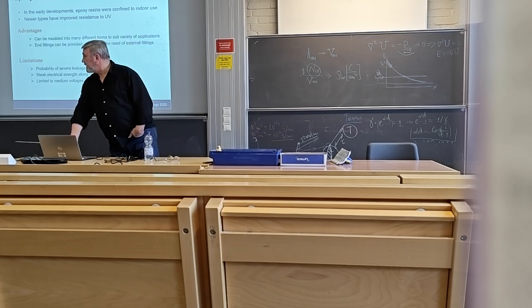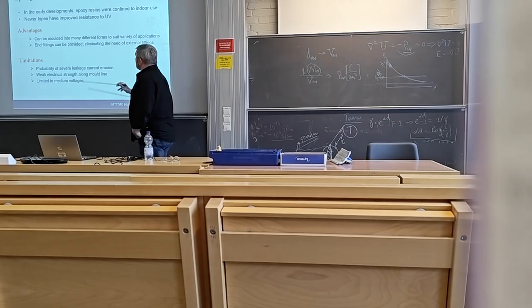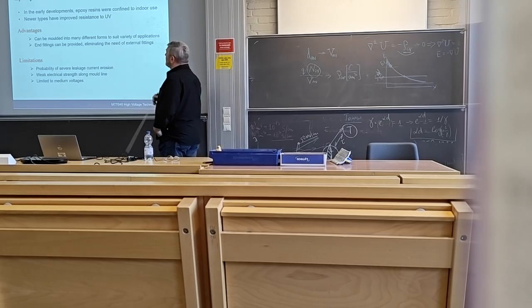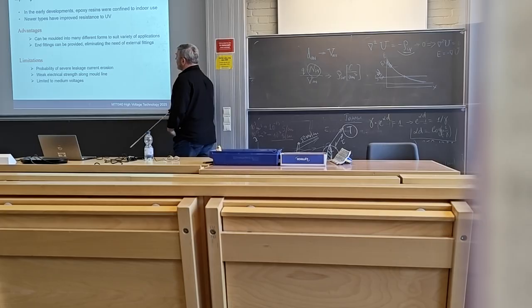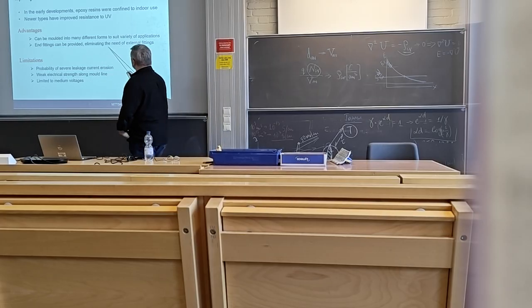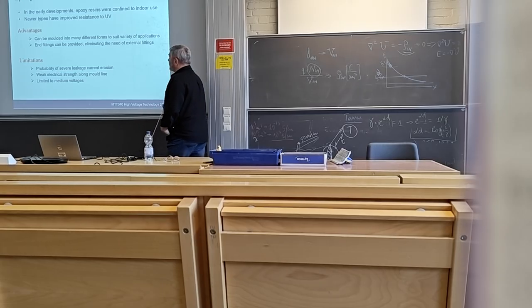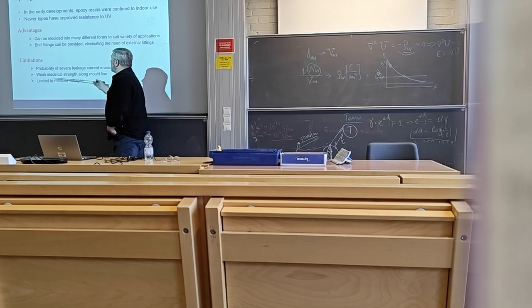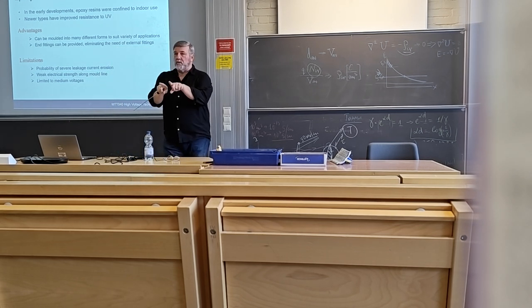Epoxy insulators, this is special type. Epoxy is not used very much today. Yeah, can be molded in different ways, shaping. So that's the important advantage of this. Yeah, and fittings can be embedded in the insulator molding. That's also a good advantage, but yeah, this is the main drawback. There is always need for molding.